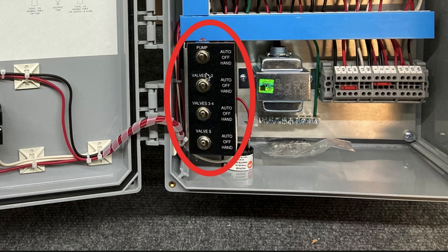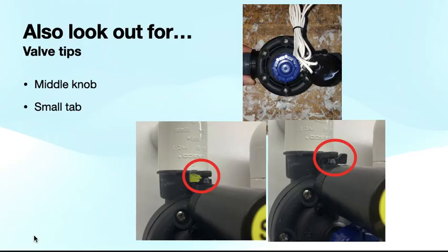Using these, in normal operation, you have all these flipped in the up position so that they're in auto. And then when we're testing, after it's been wired up for our startup procedures, after the installation's been complete and the electrician has come out, we're only going to put things in hand that we want to test, and whenever we're not doing something, we'll have them in the off position. But this is the kind of setup that you'll be looking at, to give you an idea.